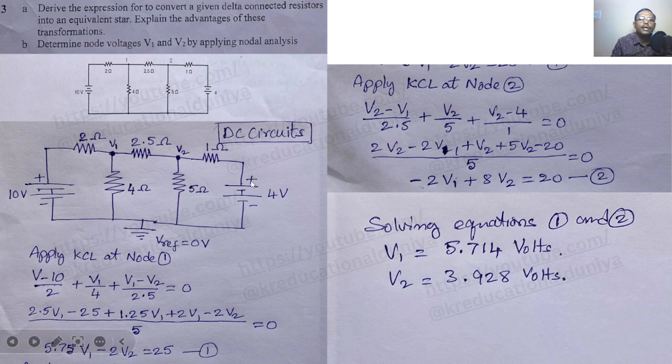So write down the equation, considering that at node 1 the higher potential voltage is V1, and at node 2 the higher potential voltage is V2. If you observe, there are totally 3 nodes: V1 that is 1, V2 that is 2, and another node, which you get if you join all the down points, that is all the down branches, at one point.